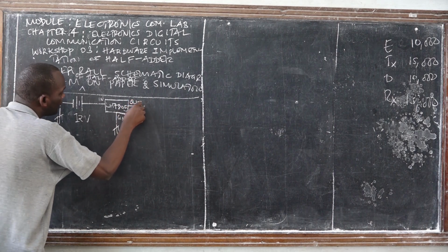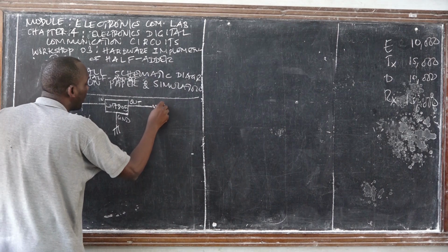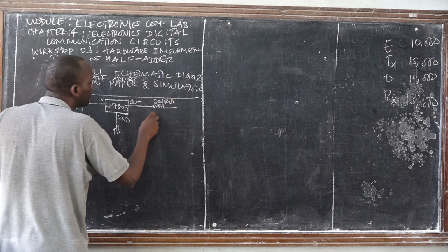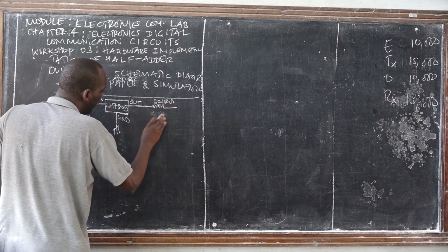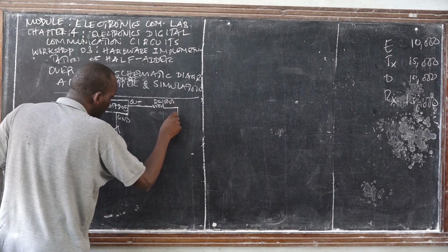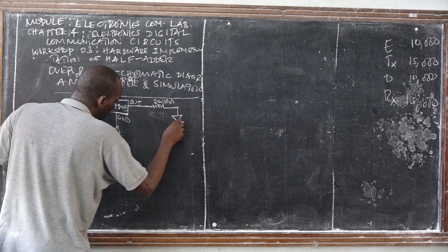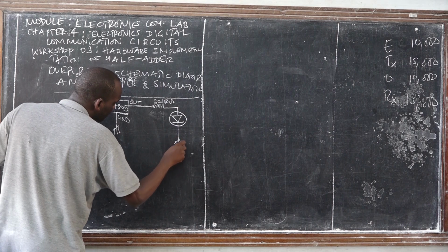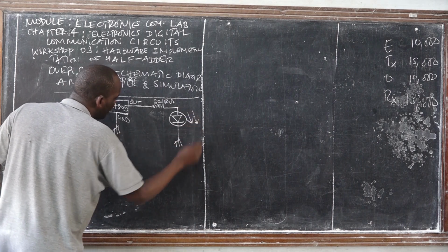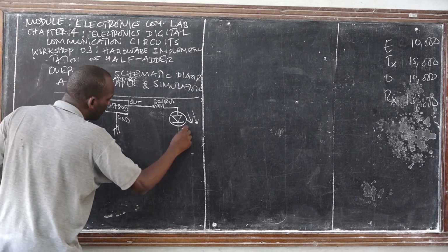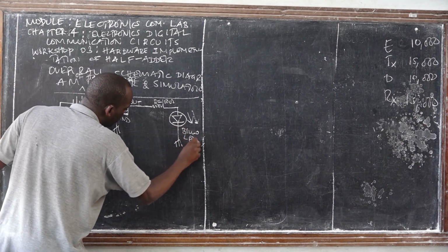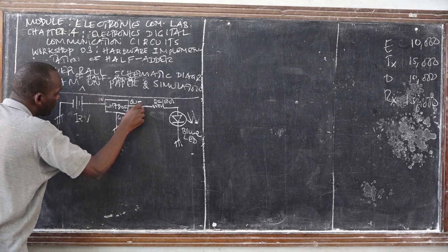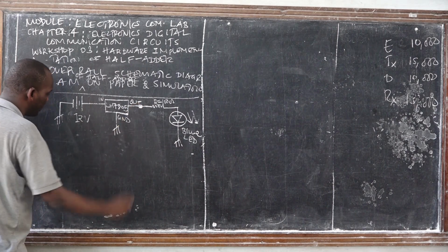Then we expect to have our power indicator. This is the resistor. We may use 100 ohm. And this will be blue. So it will be 100 ohm, and we are going to use this, which we call the DC power indicator LED. So this is a blue LED. But remember that our output power we draw at this point, this is a positive voltage.